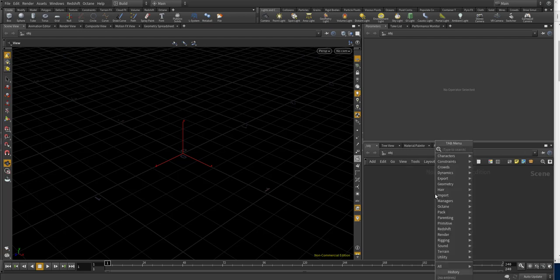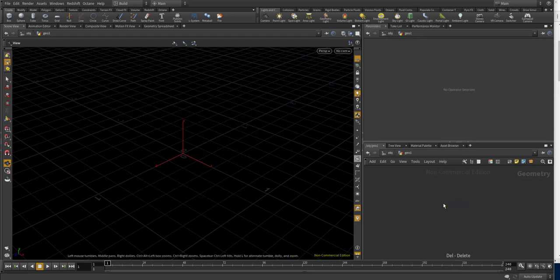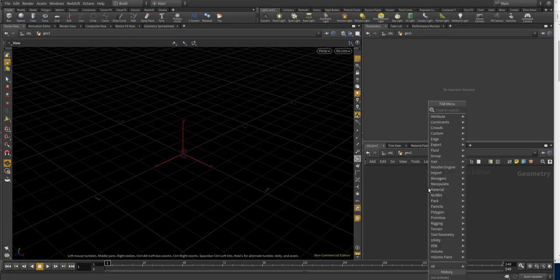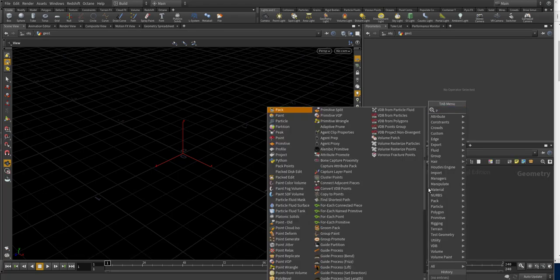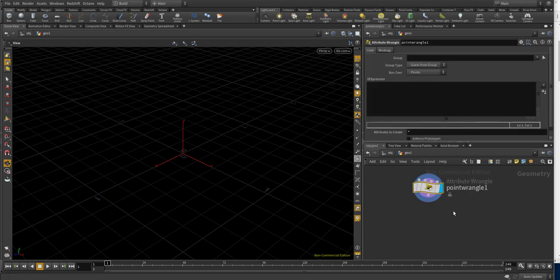So first of all, let's create a spiral curve. First, I need to make a geometry, as always. Let's get in here, delete the file, and let's start with the point wrangle. But since there's no point at first, change this to detail, and let's create some points to be a base of the spiral position, the spiral curve control point positions.